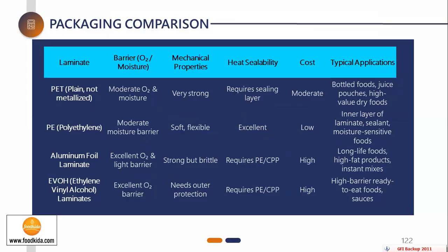I mean, in terms of the transparency of the packaging for certain materials. Transparency means you're exposing the product to light, which enhances oxidation in the product, and the shelf life reduces. So how do we come to know that this product is suitable for a transparent pouch, or this product has to go into an aluminum pouch where the oxidation needs to be less?